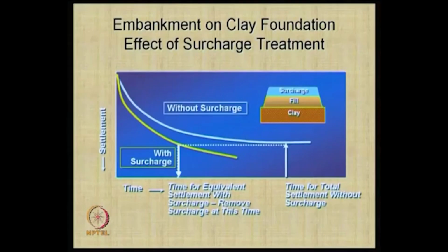And also in India you have another one, called coir. This is the same coir which we normally know. Both coir and jute geotextile are abundantly available in India, and people can develop some of these prefabricated vertical drains and use them in the field. They may be good for 9 months to 1 year, and we have seen that they have all the required properties, comparable to the synthetic materials, and they are helpful. So, essentially we will be seeing some of these materials here.